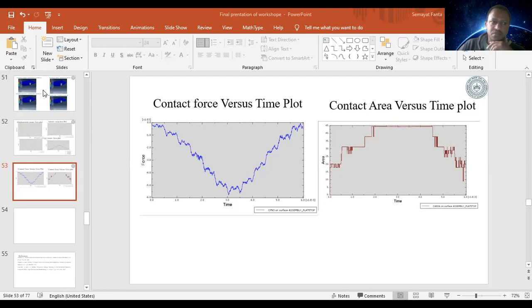Create job. Let me give the job name, say UMAT. Continue. Now, in the case of a continuum shell element, I directly click OK. But here I have to click on General and go to User Subroutine file.